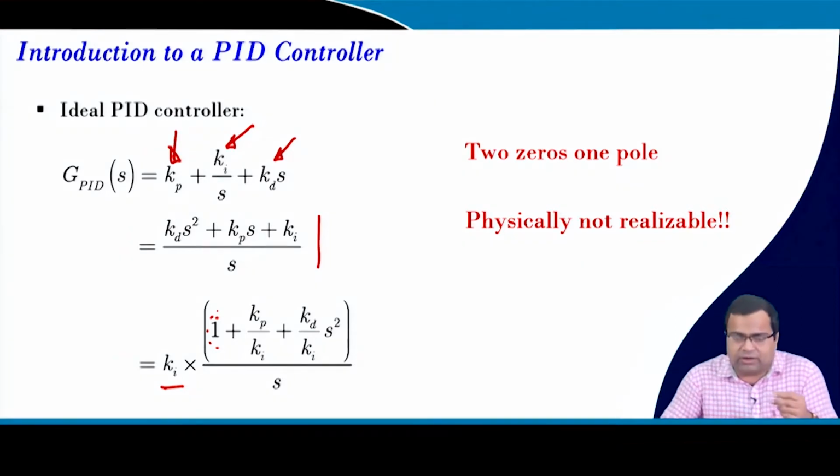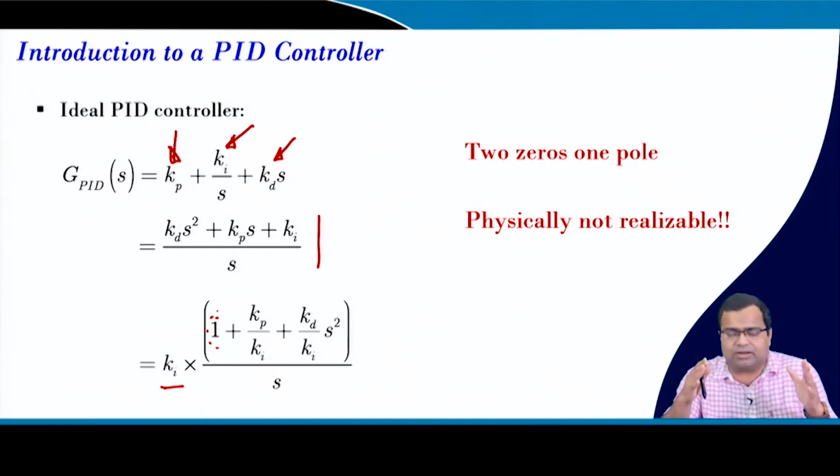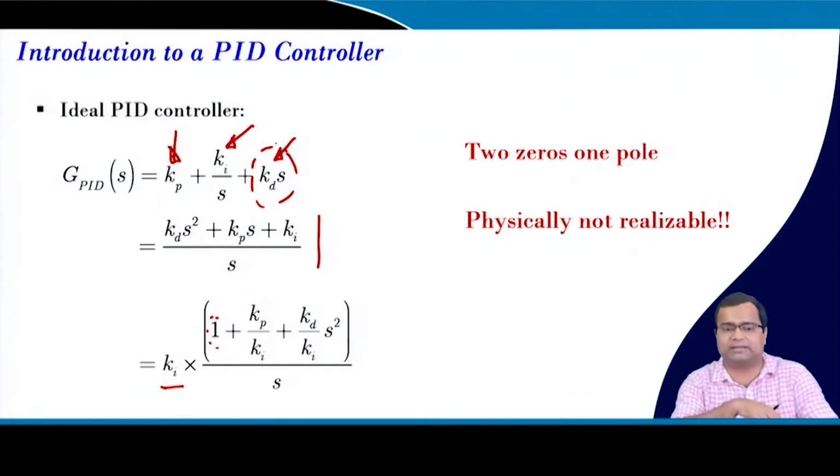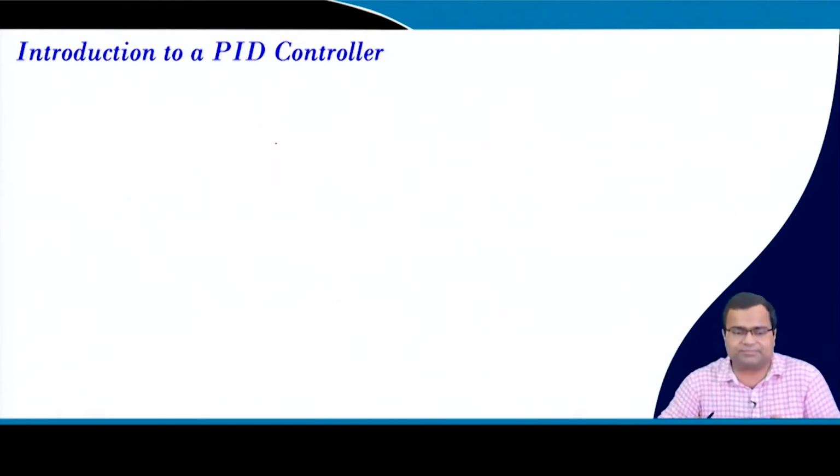Now, we will discuss this in actual PID controller reality. We cannot implement an ideal derivative. So, there will always be a band limited derivative where we need to consider a derivative filter, that means a low pass filter, and this comes typically when you use an op amp. The op amp itself has a finite bandwidth that comes into the picture.